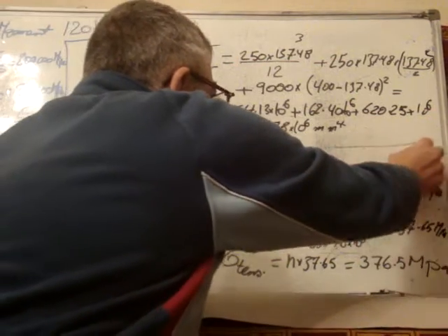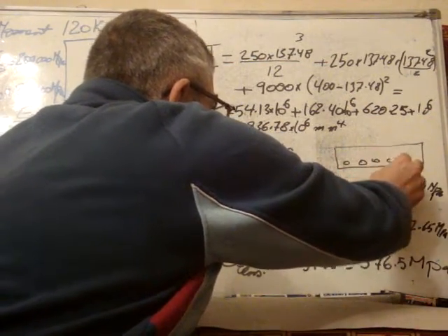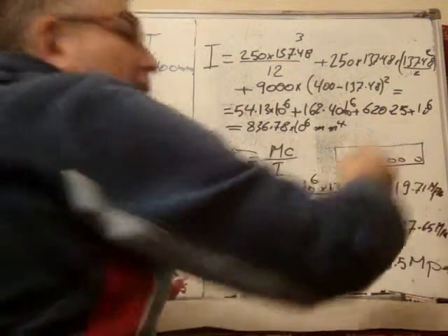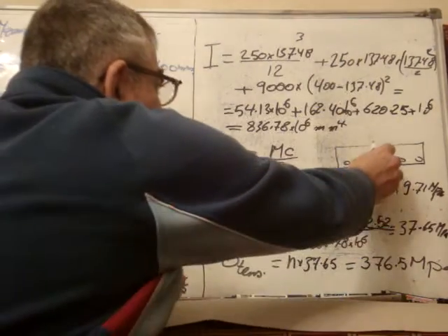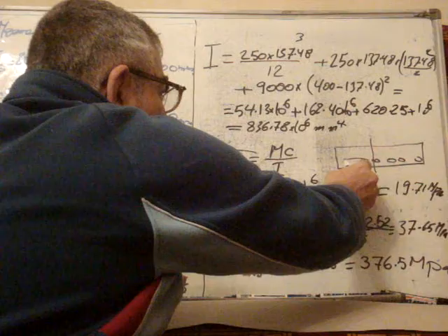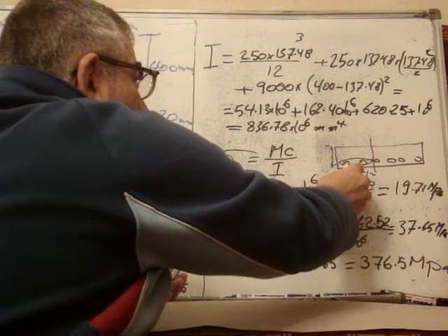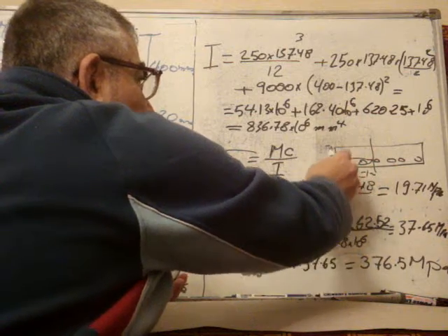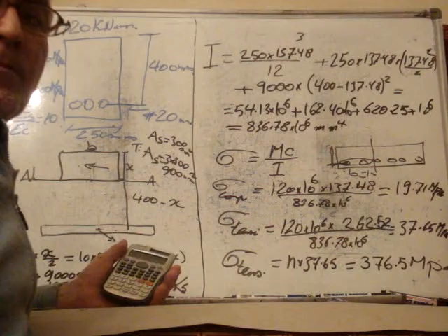That means if I have this slab with reinforcing bars, and this is, for example, 4 meters, we take only 1 meter and assume b equal to 1 meter, and we calculate how many bars we have in 1 meter, and this is the thickness of the slab. We take the distance from the steel to the top, and we use exactly the same way as the beam.